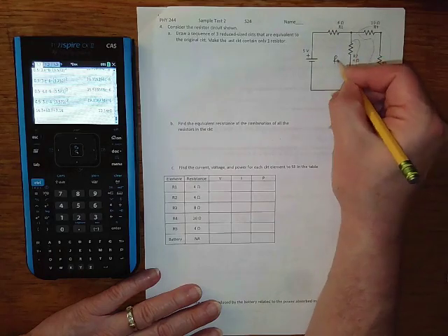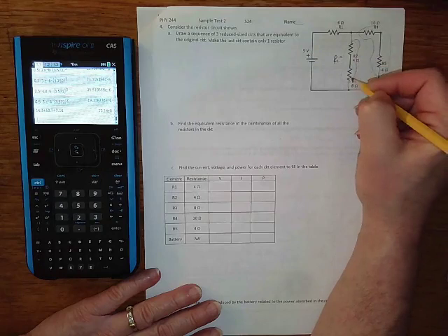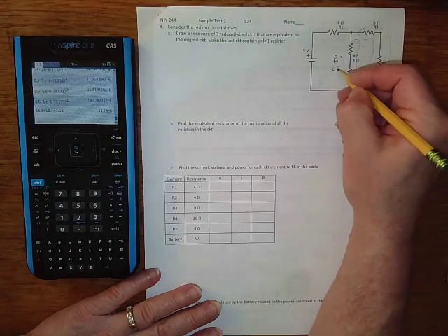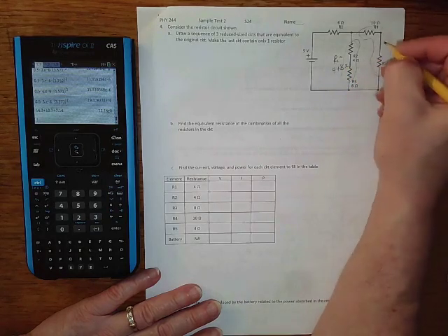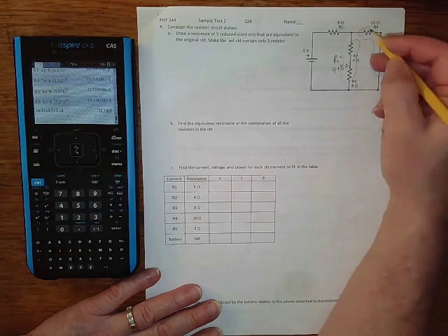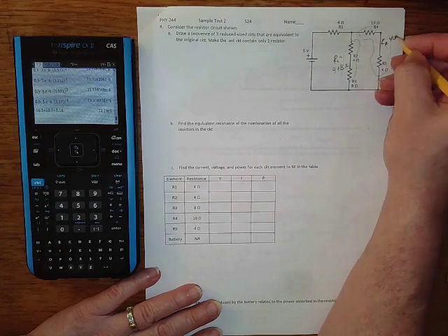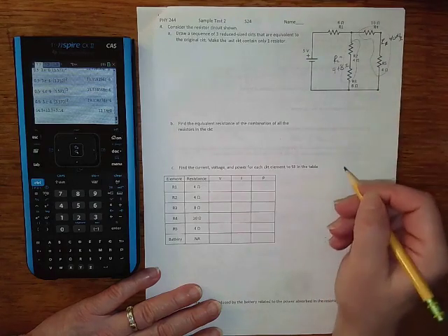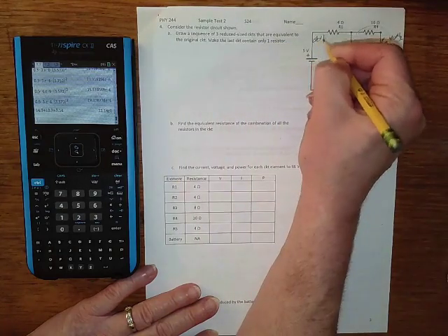We'll call this R left. It's going to be R2 plus R3, right? When resistors are in series, they just add, so it's going to be 4 plus 8 ohms. Whereas R right is going to be, again, R4 plus R5, which is 10 plus 4 ohms. All right, so if we redraw the circuit, if this is circuit 1, circuit 2,